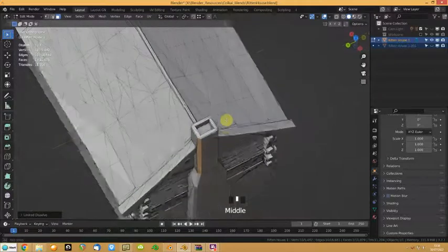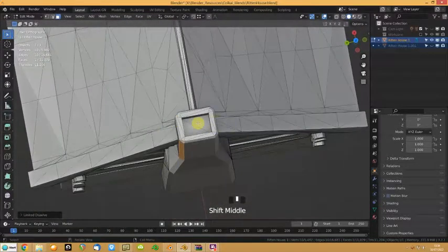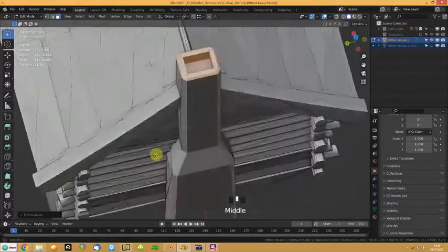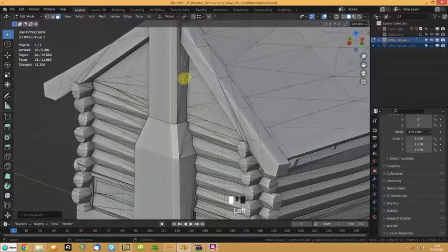Now in here, I can see these are all triangles. So what I'm going to do is select them, then Control plus, so it's holding Control and pressing the plus on the numpad. And I'm going to go out there, then Alt J to turn tris to quads. And that's done all of that tidy up for me. Again, select everything, limited dissolve.